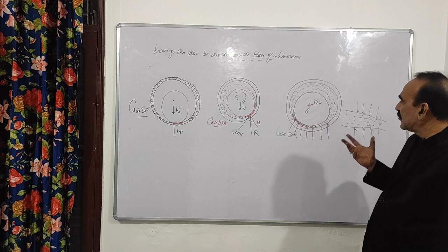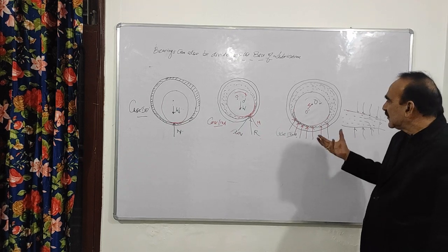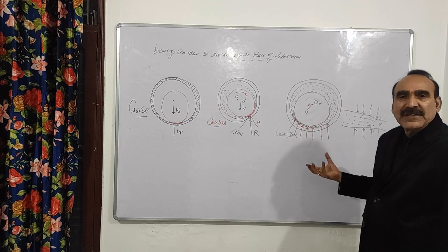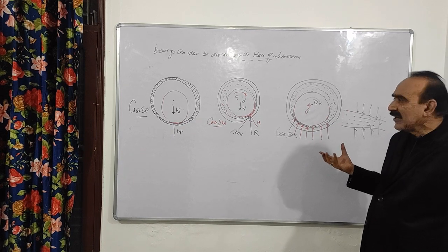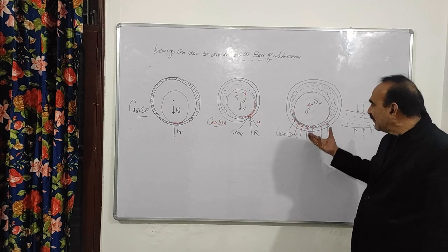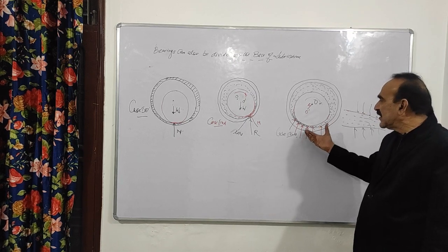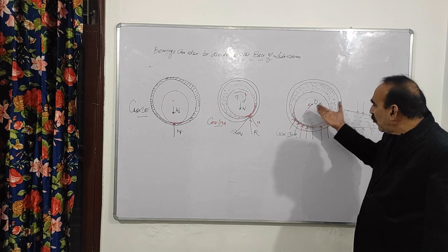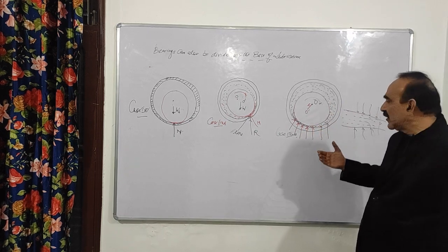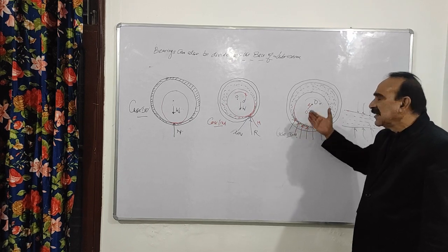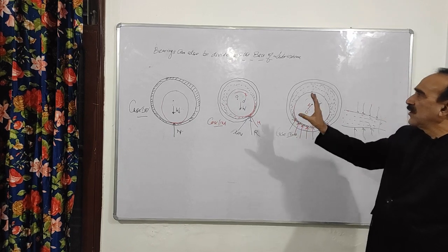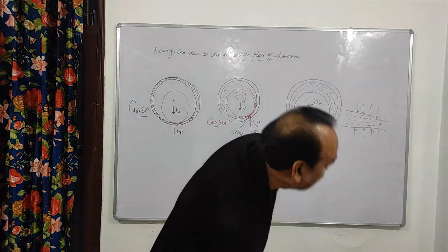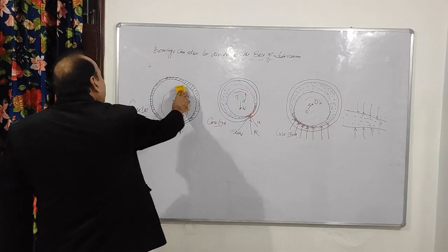Due to the creation of the wedge, some pressure is created in the thick film lubricating oil, and the pressure is normal to the surface. So the load of the journal is being supported by the pressure which is created in the upward direction. So this is about your hydrodynamic bearings. अब small जो इसका एक portion रहता है, that I will also explain to you.